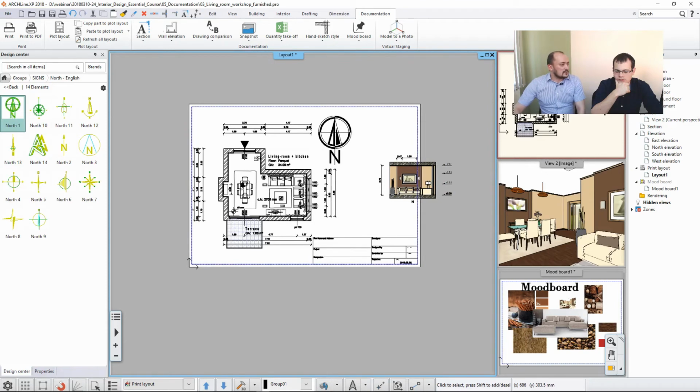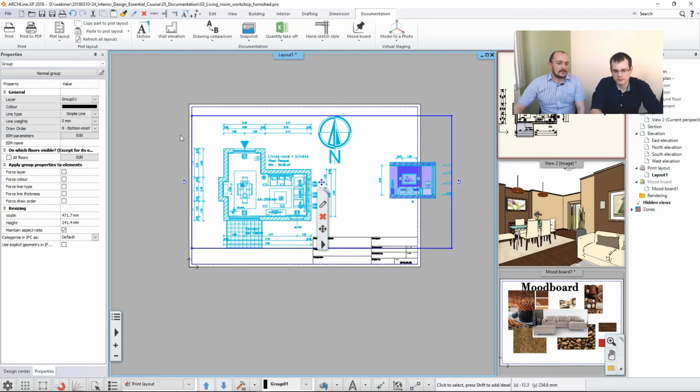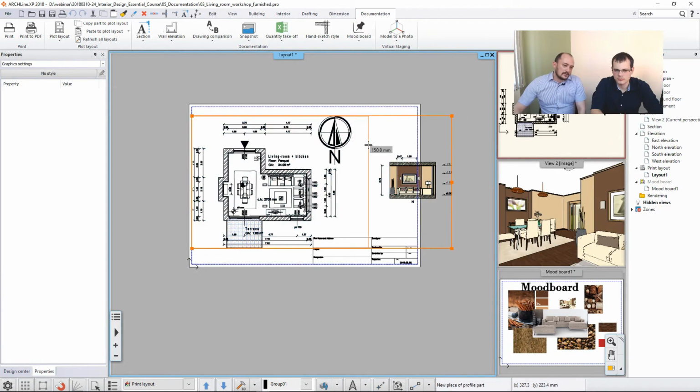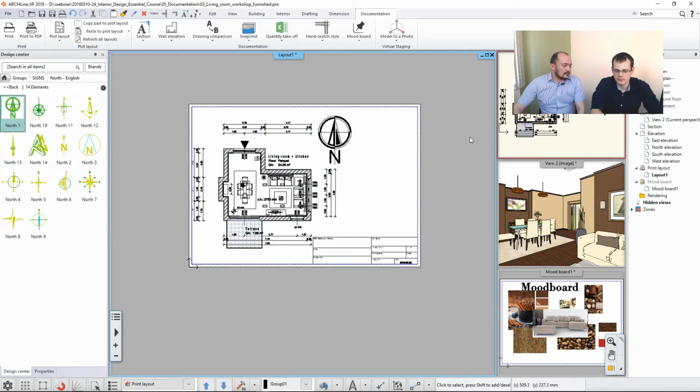That was part of the original drawing, so I can click on this layout and move this boundary to the left and chop that part off. After that, I can decide to use this again, but in that case, only this part. Now there are two options for that. First things first, if I'm dragging this inside again, let's say this should be 1 to 200 now. That should do. I can place it with two different scalings.